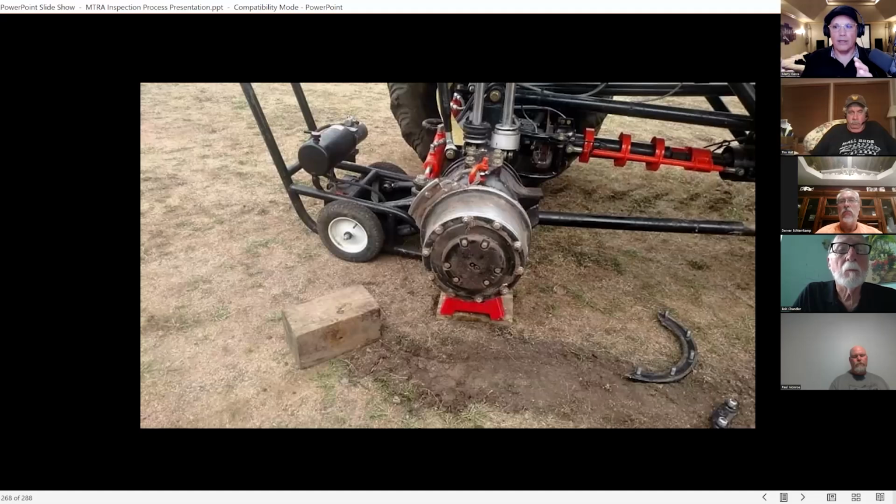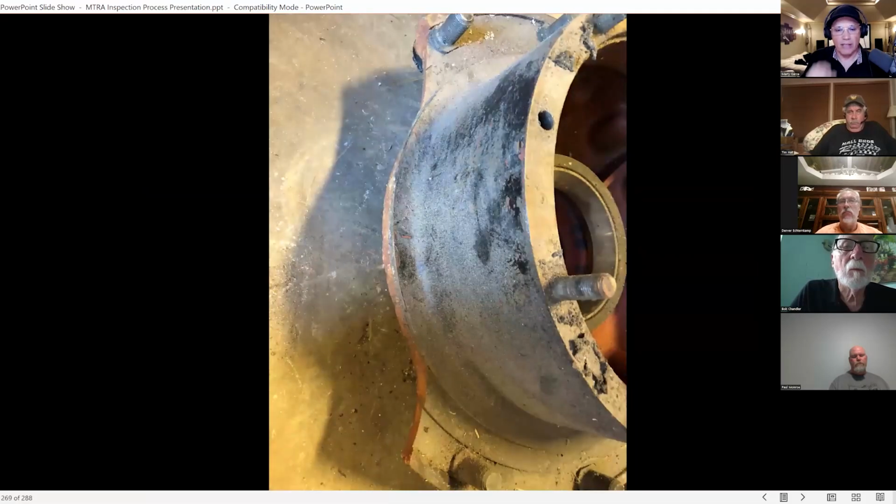To finish my thought there, when the lug nuts get loose, the wheel can move. It works against that flange, and that flange has a stress riser, a weak spot in it that will allow it to snap, and the whole ring will break off, as you see in that picture. And there goes the wheel. Wheel restraint won't stop that. And we see that failure very often, too often.